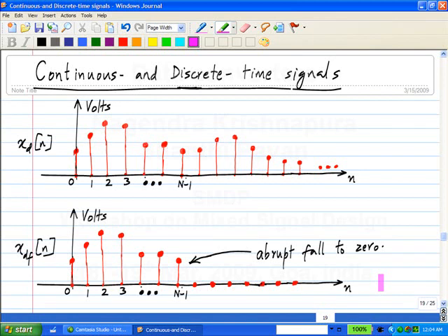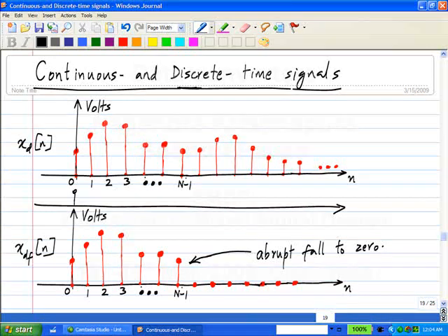So that abrupt change, you cannot allow that. I won't go into the details of it, but all of this leakage is because of that abrupt change. At the two ends, you have an abrupt change here and an abrupt change there. So when you multiply this signal, the upper signal, by a rectangular window, you get abrupt changes at the boundaries. If you get abrupt changes at the two boundaries, you can get a lot of spectral leakage.